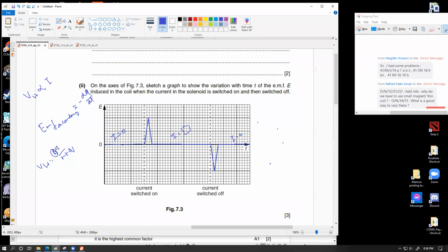Exactly. So the Hall probe is basically the physical device that we have most commonly available that we can use to measure the magnetic flux intensity at a given location. We measure the voltage by voltmeter, current by ammeter, N is the number of charge carriers. This is a constant that depends upon the Hall probe material that you choose. So this is a constant that is put into the algorithm of the Hall probe. T is the thickness, that's measurable, and Q is the electron charge. So except for this one, we can physically measure or we know all of these other variables. So B can be easily calculated out of this equation. That's the beauty of it.